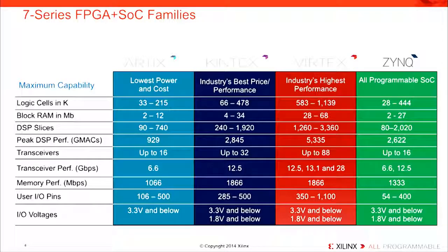But the good thing about Artix is if you are taking some off-the-shelf ICs or components and putting them on the board, you do not need a level shifter, because if they are 3.3 volt compliant, you can just connect them.